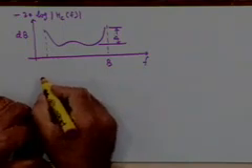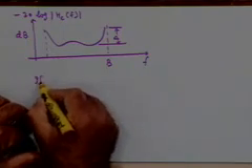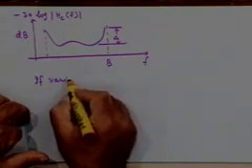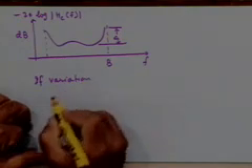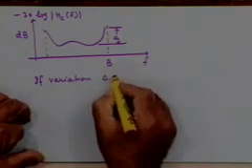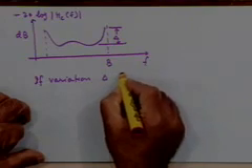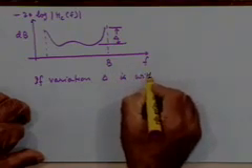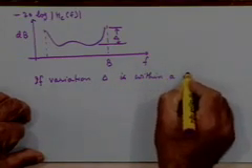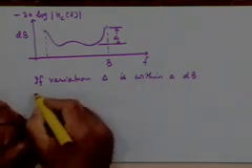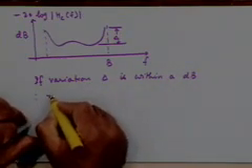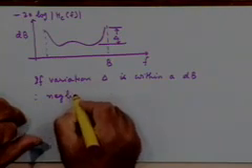So if the variation of the attenuation as a function of frequency, let us call that delta, is within a dB, within 1 decibel, the amplitude distortion is negligible and we can ignore it.